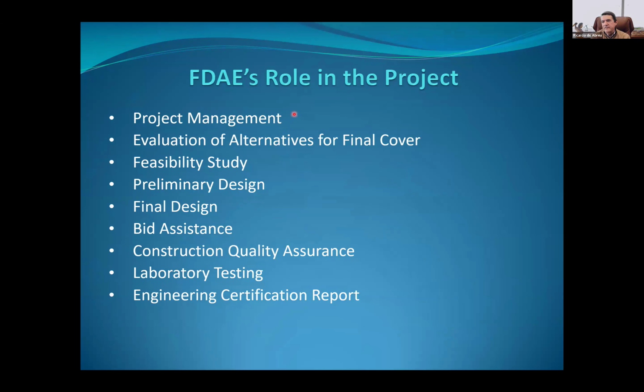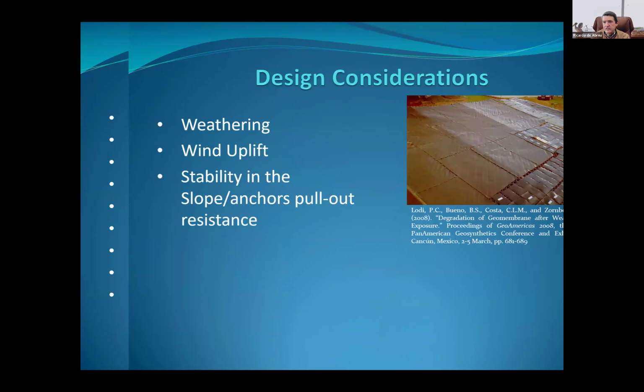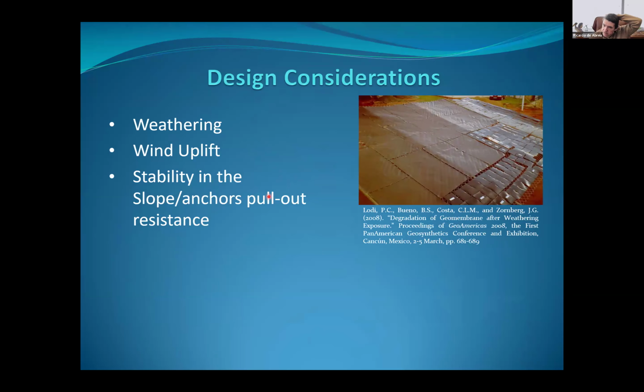Our role in the project went from project management and evaluating alternatives for final cover, all the way to the engineering certification report that goes to DEQ. So that was my company's role on that. Some design considerations for the exposed geomembrane: one is weathering, wind uplift, stability on the slope, and anchor pullout resistance. Those are things we had to take a closer look at to see how we design that.